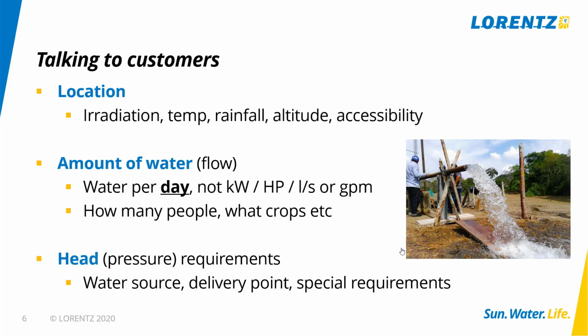And what you're trying to do is understand the amount of water that's really being used for the application, but in a water per day situation. And of course, the reason we want to do that is because we want to try to pump all of our water using solar power. We don't want to be installing batteries. We don't want to be installing generators unless we absolutely have to. We want to try and meet all of the water needs using solar power. The reason we do this is because it's most efficient, most cost effective, and gives the customer a long-term reliable solution.